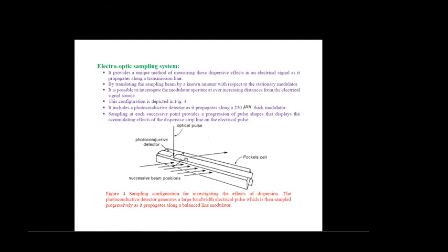From the equation we have given, we can see that the dispersive characteristics of a microstrip transmission line are highly sensitive, that is, proportional to the product of the electrode separation and the square root of the substrate dielectric constant.